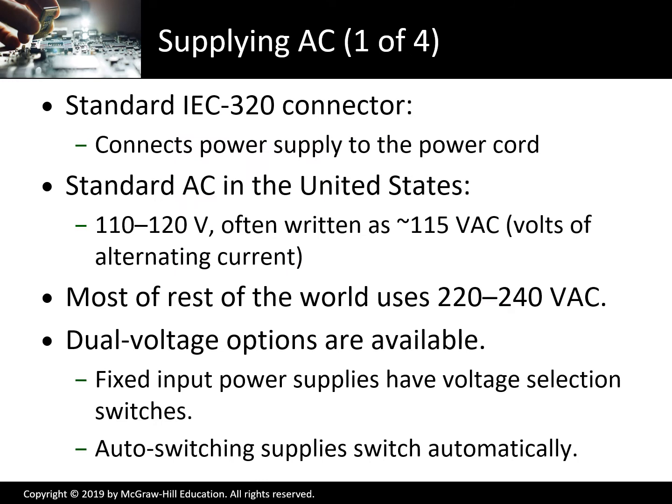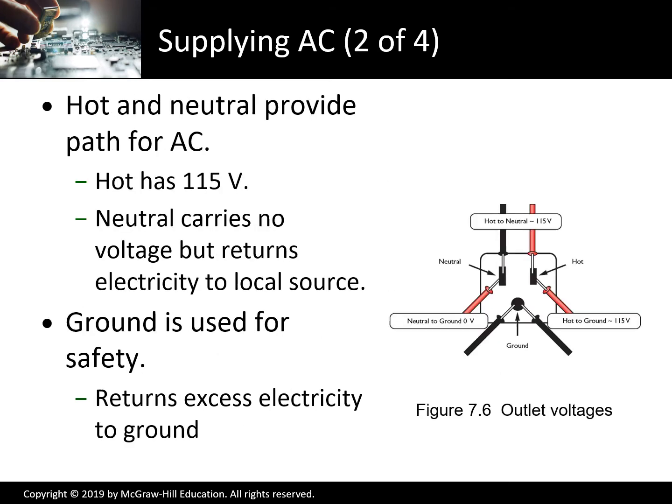Now, the standard connector is an IEC 320. It connects the power supply to the power cord. Most of the world uses 220 to 240 volts, versus 110, 120 here. Most power supplies come with a little red switch in the back, and you can flip it between the two. So if you take the computer offshore, or somebody wants to buy power supplies in another country, one size works for everybody.